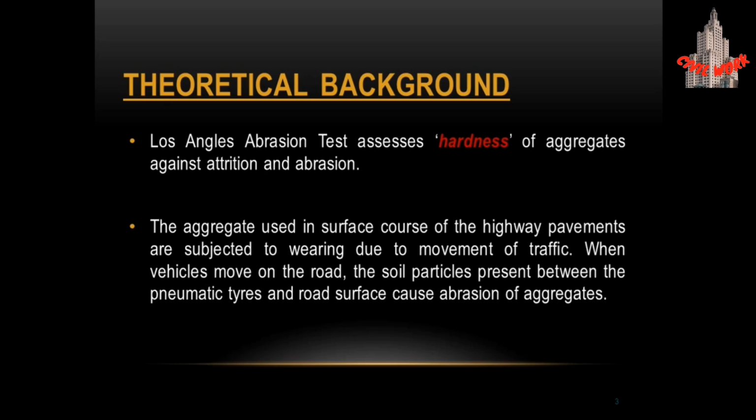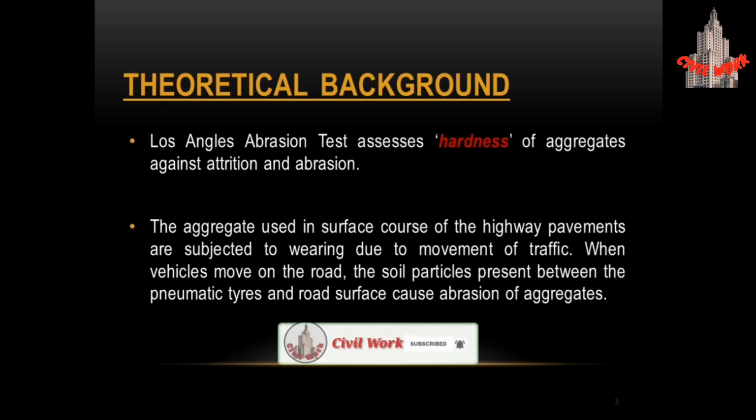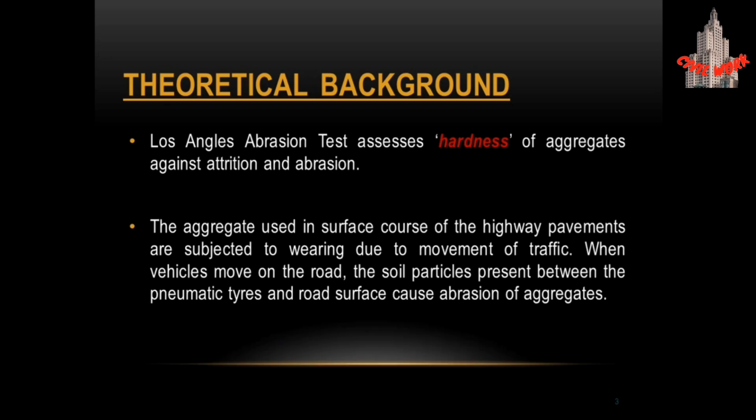In construction, we generally prefer harder aggregates due to the following reasons, where we have high traffic roads, airport runways, high strength concrete, and decorative applications, whereas we prefer the softer aggregates in the places of low traffic roads, building construction, landscaping, and drainage applications.